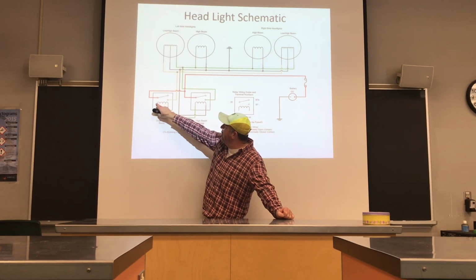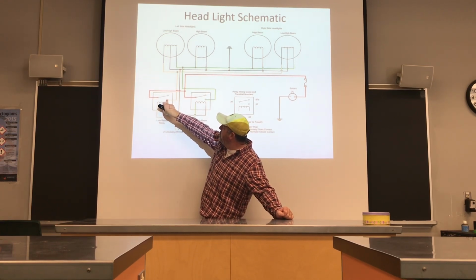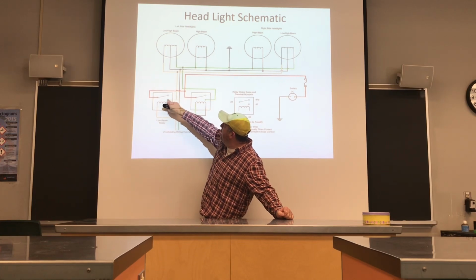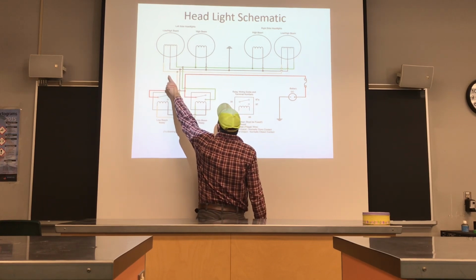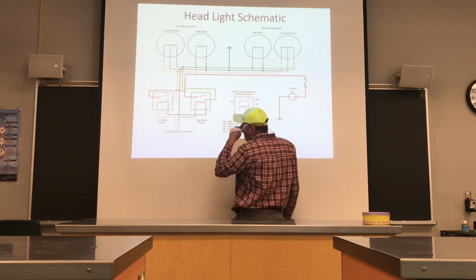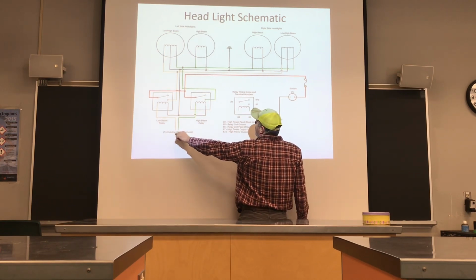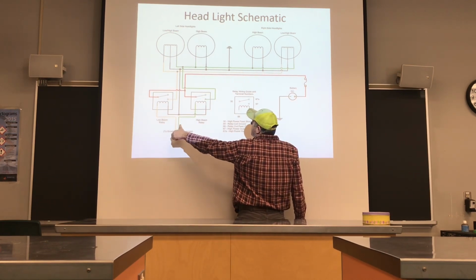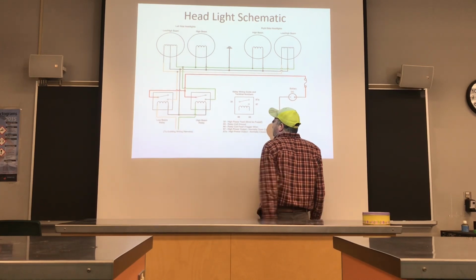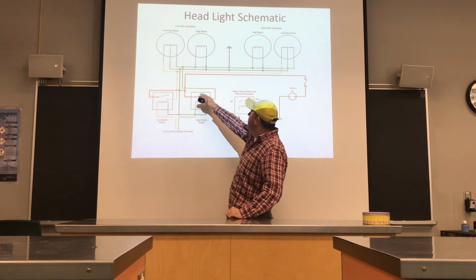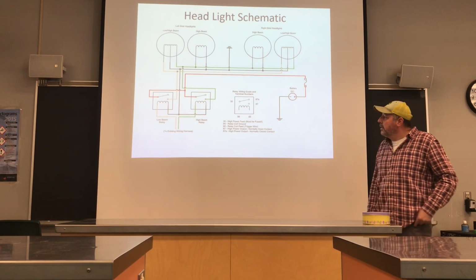The magnet in the coil pulls the terminal down to our low beam wires, and we supply power to both left and right low beam. When we turn the low beams off or use our high beams and switch the rocker switch, we supply power to the coil side on our high beam relay, and then it sends power to the high beam.